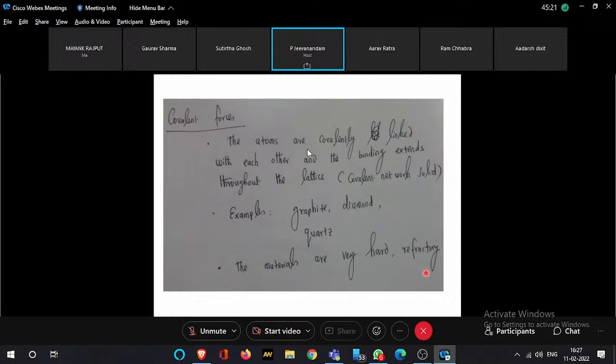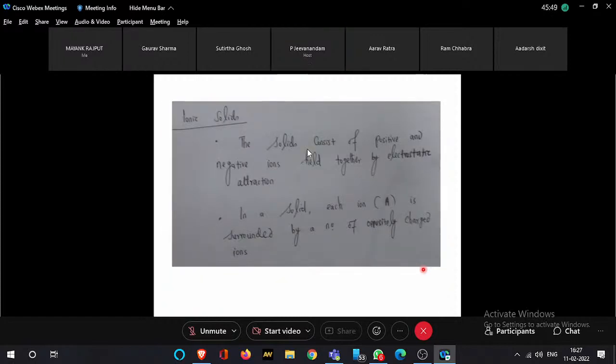So you need high temperature materials to be used in a furnace. And those materials are actually refractory materials. You will see that they don't yield to the heat treatment. Nothing will happen to it. Of course, not every material can be used as a refractory material. I can give you an example. Aluminum oxide is a very good refractory material. Silicon carbide is a very good refractory material. There is a commercial name for silicon carbide. Does anybody know?